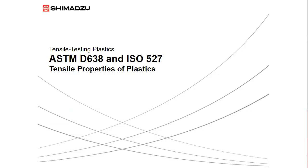I'll begin first with ASTM D638, which is written for unreinforced and reinforced plastics. I'll point out that there are separate standards which are recommended for thin sheeting, films, and composites. And I'll also provide some comparison with ISO 527. ISO 527 is structured a little bit differently. It has a -1 version, which is general definitions for tensile testing. And then it has separate versions, -2 for molded and extruded plastics, -3 for sheeting, and -4 and -5 for composites.